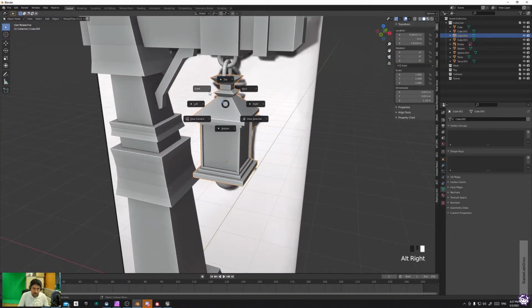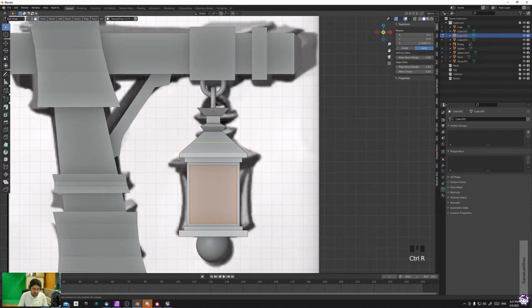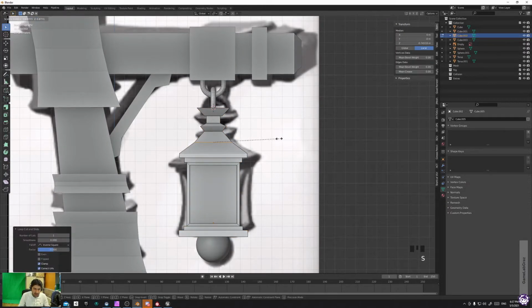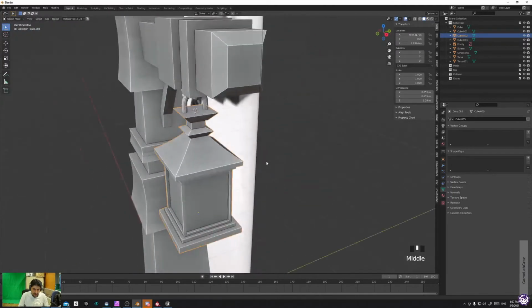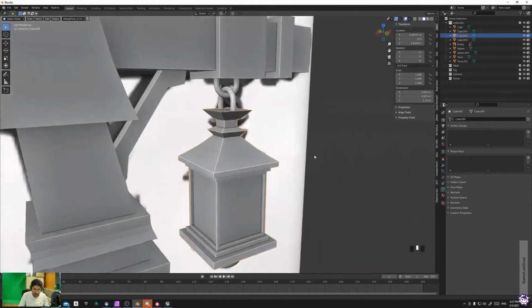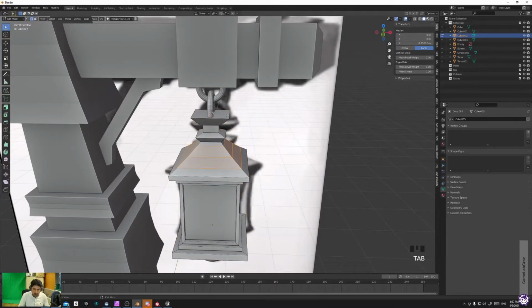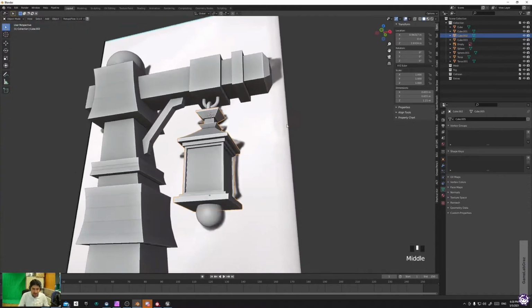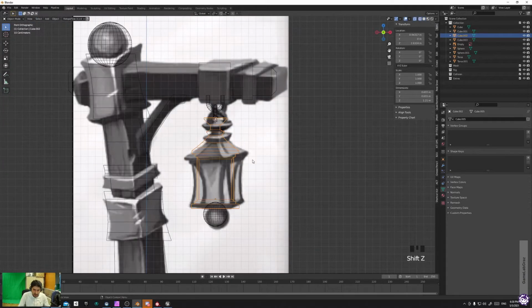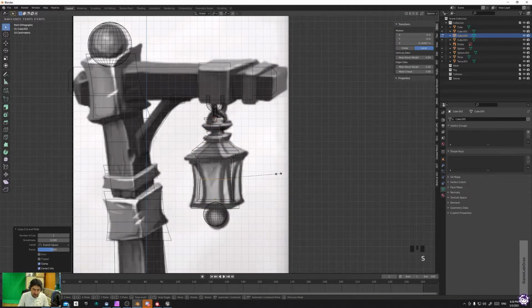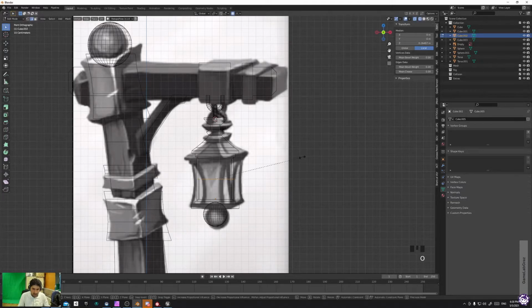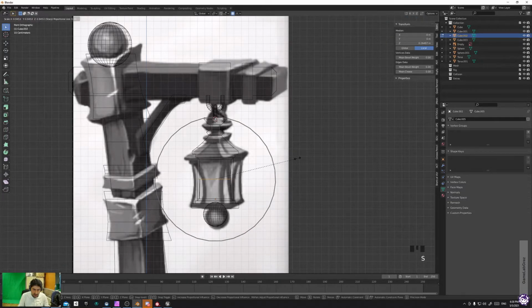Okay. The other thing I would like to do is adding another loop cut here, scale it down, and then bevel it. Give a little bit of curvature feeling. Not so bad. Also, I would like to extrude this part a little bit upward, like this. What else can we do? For example, if I add one edge here and scale it here, proportional scaling.